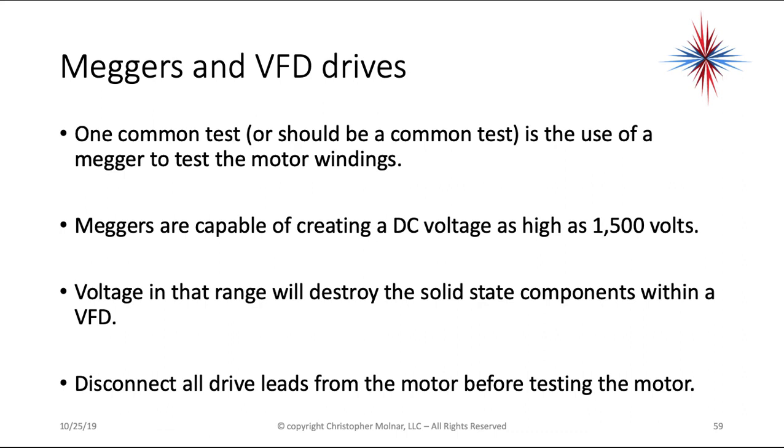Disconnect all drive leads from the motor before testing the motor. You do not want any voltage that high to go back into the VFD itself. So you have to disconnect all leads before testing the motor. You should be doing that anyways because you're ohming something out. The component should be isolated.